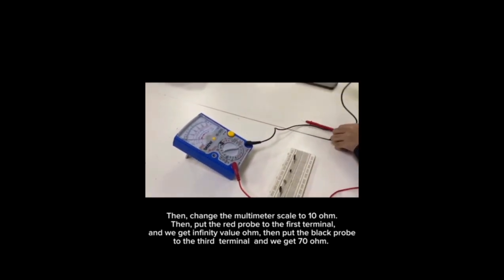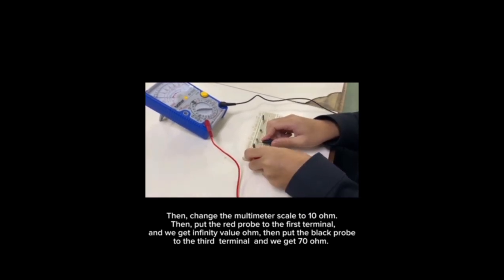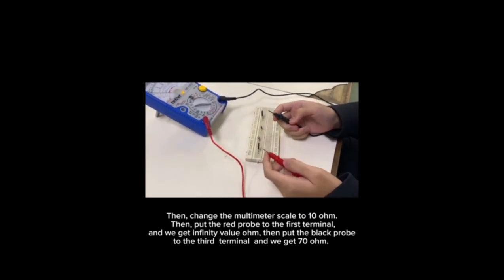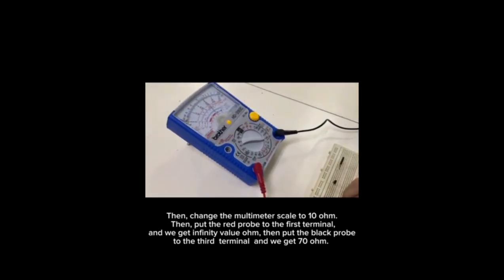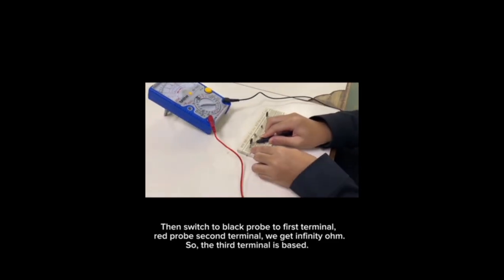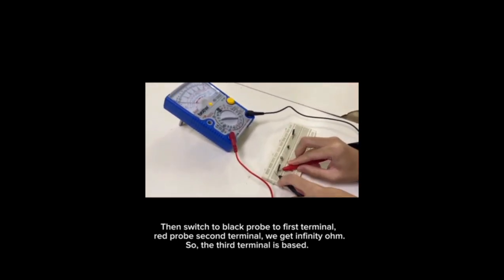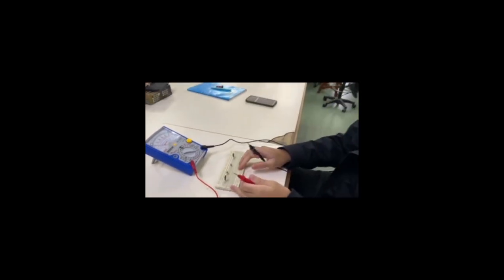Put the red probe to the first terminal and the black probe to the second terminal, and we get an infinity value of ohm. Then put the black probe to the third terminal and we get 70 ohm. Then switch the black probe to the first terminal and the red probe to the second terminal, and we get infinity ohm. So the third terminal is the base.